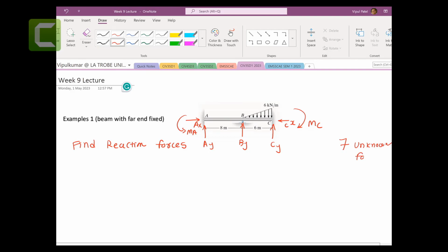And then you have some equilibrium equations. So it's a highly indeterminate structure, with a degree of static indeterminacy equal to 4. If you use force methods, of course you can, but it will have 4 compatibility equations and be a huge job for you. Probably not possible by hand.